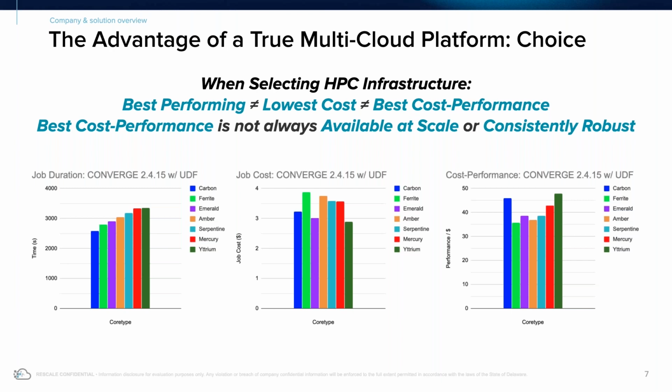Certainly if you were running 2.4, as Cooper mentioned, that was more memory bound in terms of its processing. So in those cases, you might want to have access to resources that have more memory. If you're now going to 3.0, that's no longer needed. So you probably just want a processor with a fast interconnect or a faster clock speed. But that's not the only variant. Of course, also during your life cycle, during your development cycle, things change.